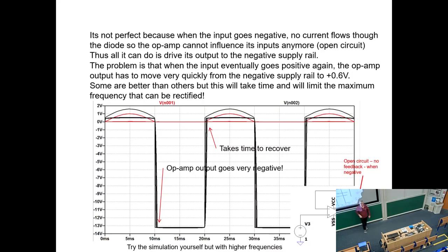So there's a little bit of distortion at the edges. Okay? But you have to start looking quite closely to see this for low speed signals. High speed signals, it starts to become important because this time becomes a significant fraction of your waveform. A certain number of degrees at high frequency. Right, so that's the key.